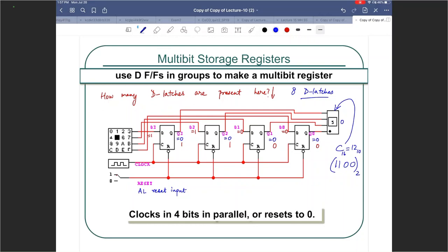The reason why I do this exercise is because once you make the hierarchy go up, it's very easy to start ignoring how we constructed that hierarchy, that pyramid going up, right? So it's good to ground ourselves every time. Okay, check back. What is this constructed of? A D flip-flop. How many latches do I need to make that D flip-flop? 2 of them in a master-slave configuration, right?